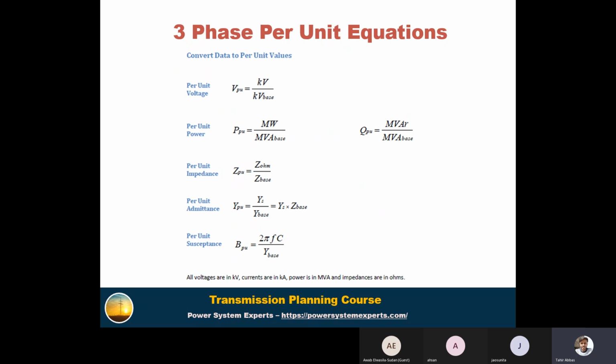In this way, you can calculate R, X, B and then put them in the transmission line, and you can put them in the transformer. These are not on different bases. These are the per unit values that are calculated based on the given data available on the nameplate.